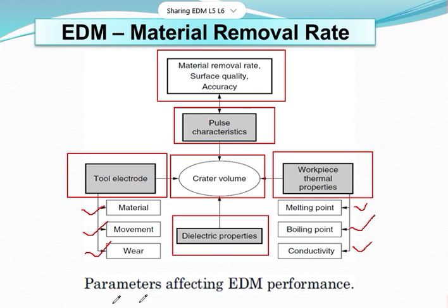So these are all the parameters that affect EDM performance. Keep in mind that the ultimate result is your material removal rate, surface quality and accuracy, but the parameters controlling the entire thing are the pulse characteristic, tool electrode, workpiece thermal property and, of course, the dielectric fluid.